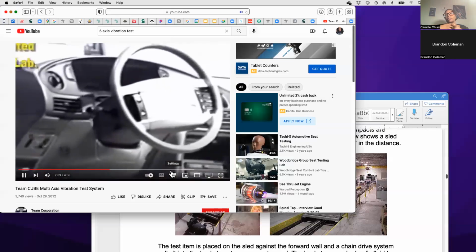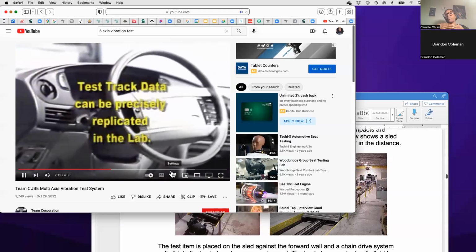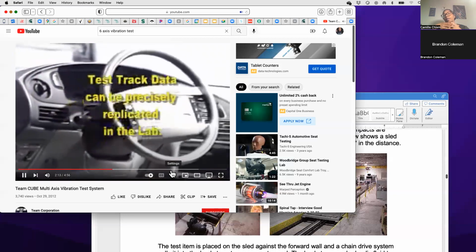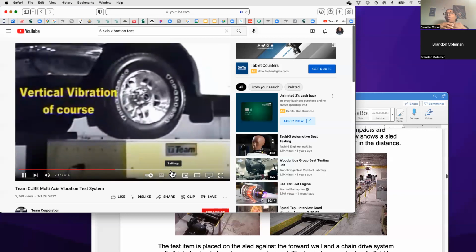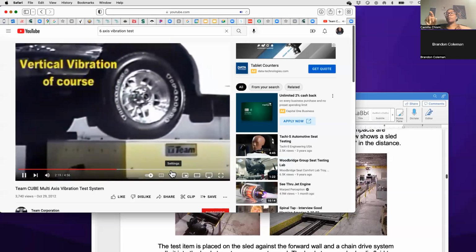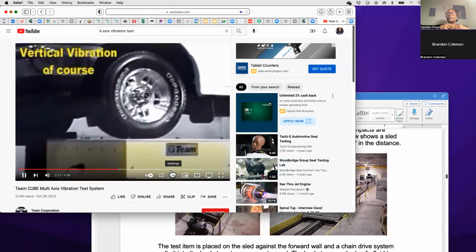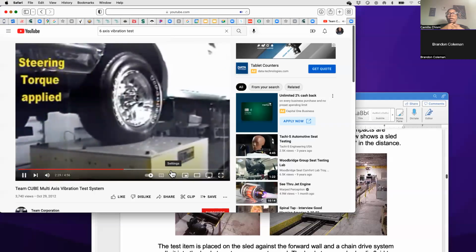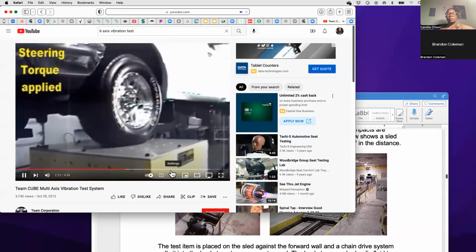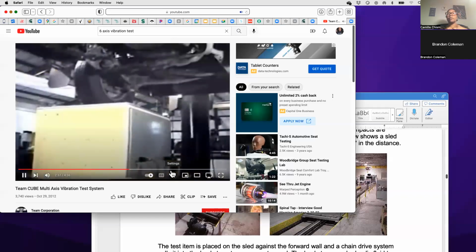Are they packaged in such a way that if they're class A, are they going to vibrate and scratch each other? Is the surface going to be scratched? Or you see they're bouncing up and down for that. Is there going to be so much bounce in the trailer that if it's an electronic part, that part is going to hit resonance frequency, or will it break some of the solders and welds? Those are some of the sort of things that we're trying to simulate.